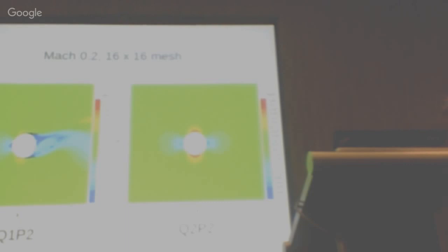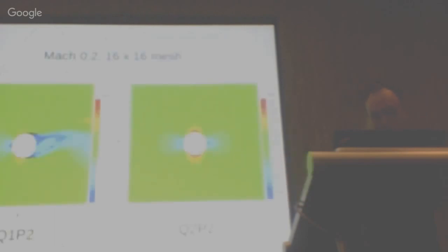So by simply changing the mesh, and this is for the coarser one, you can see that the flow detaches from the geometry. And this is purely numeric, or rather induced by numerical errors due to the mesh representation. You can notice there's a somewhat sharp transition, the angle is quite large, and the solver sees the normal vectors on this face are quite different from this cell's perspective from this other one. So the flow eventually sees a discontinuity in the geometry, and that leads to separation. These both are in the same color map, it's Mach contours.